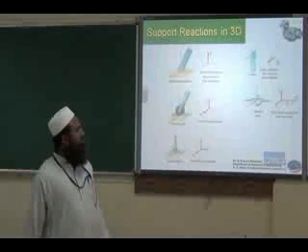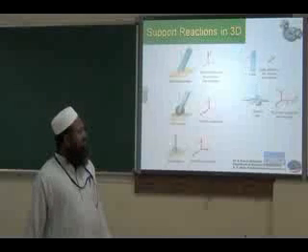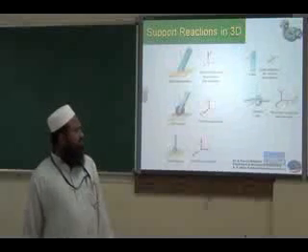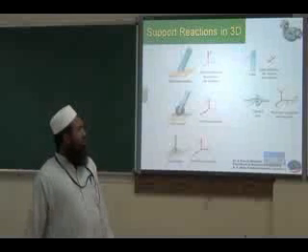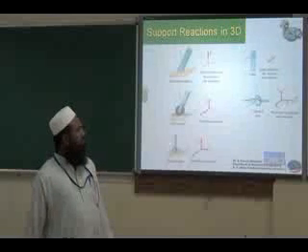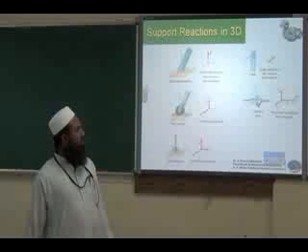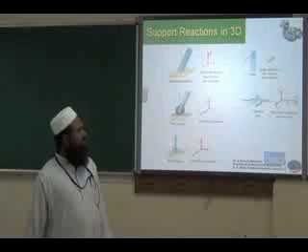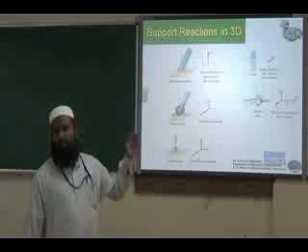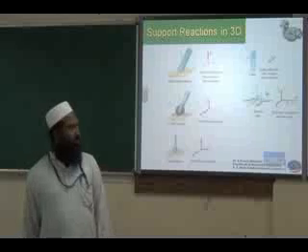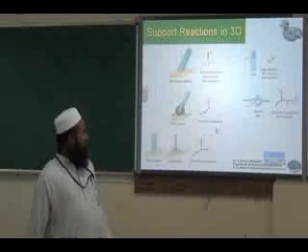A cable will have one reaction. Okay, cable connected member. This is a universal joint. It can rotate around z. It can rotate around x also, but it cannot rotate around y. So we will have one moment, and it cannot translate in any direction. So we will have three reactive forces.